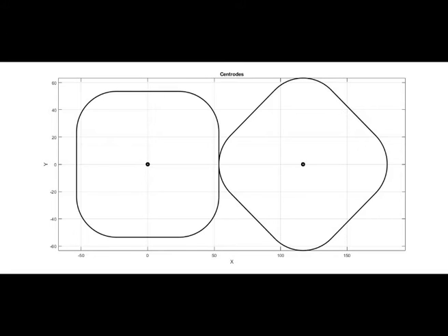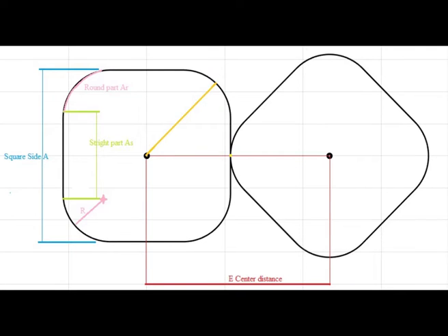The most important point in this case is to find the centrode dimensions, since it consists of straight lines and quarter circles on the edges. So, finding out the relationship between these parts means designing the centrodes. To find this relationship, let's start from the reality that there is no slippage between the gears or the centrodes being in meshing.